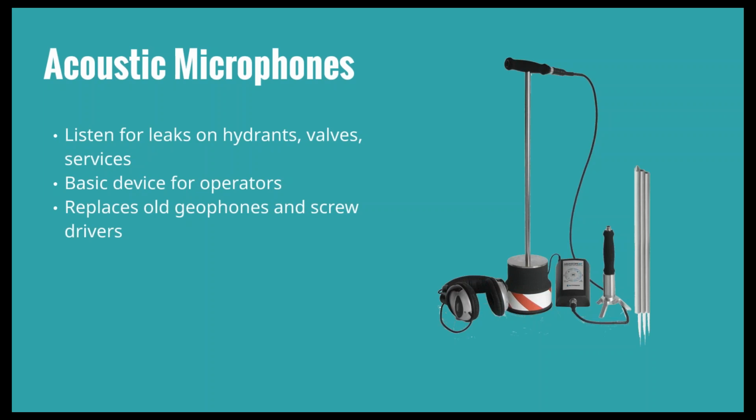So just to briefly go over the equipment, so the acoustic microphone where you're doing the ground sounding, an elephant's foot, if you're doing it on a solid surface, there's other sensors that are better for softer areas where you have decomposed granite or just a soil backfill and no paving. Can also be used on valve leaks, and is a good initial investment for doing leaks, even for when your crews are out even doing repairs on surface leaks. Going out with acoustic microphones is a good idea to help pinpoint exactly where that leak is occurring.